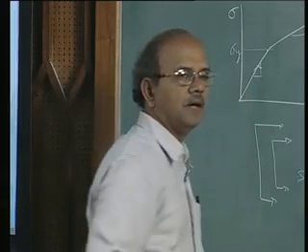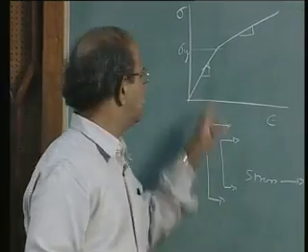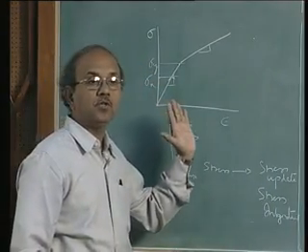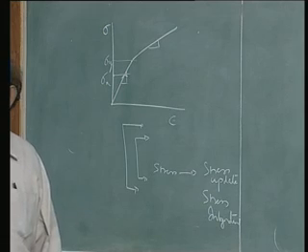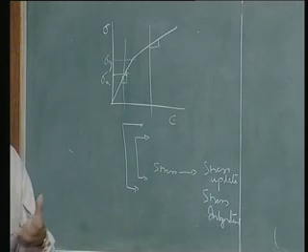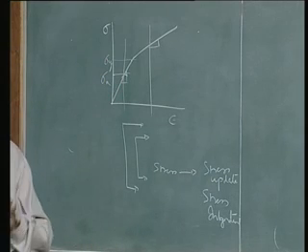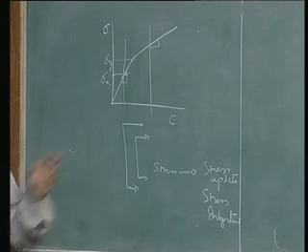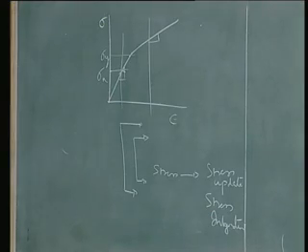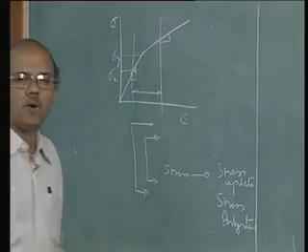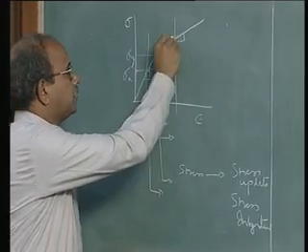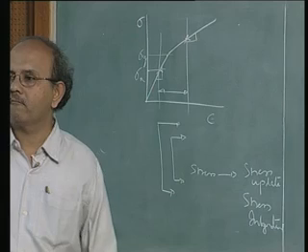Assume that I am at this point here, at step n, and I have to move ahead in stress. Assume that my deformations during that step are such that the epsilon that I get makes me move from the elastic region into an elastoplastic region. Let's say that is what I get as delta epsilon, and when I move my stress, I have to move from this point to the other point.